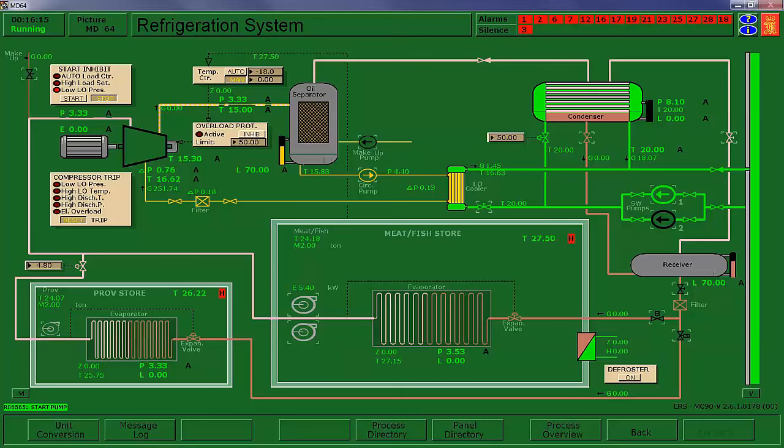And we don't want to put too much load on this compressor on startup. So I leave it in manual and I put it in about 25%. All right. Once we start the lube oil pump, our trips should all clear here. And we can go ahead and start it. Now, what I'm doing initially, that's 3 bar suction pressure. Now that's 45 pounds. I would be worried about any liquids that had formed in this system while it was shut down, and the possibility of liquid slugging back. So in the beginning, I'm not going to put any liquid on. I'm going to wait till this drops down to about 1 bar, and then I'll go ahead and put the system in automatic.